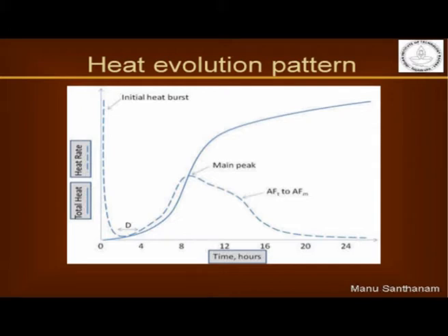As soon as that is obtained, the heat rate actually comes down. You see here that you have a period of very low heat rate. Mind you, it is not zero. That means the reaction is not discontinuing there, it is still continuing, but then you have a very low heat rate, and then you see a sudden rise in the heat rate. After a certain period, let us say 2 to 4 hours, you see a sudden rise in the heat rate, and you culminate in this peak which is named as the main peak of hydration. You see, this is the main peak of the hydration process.